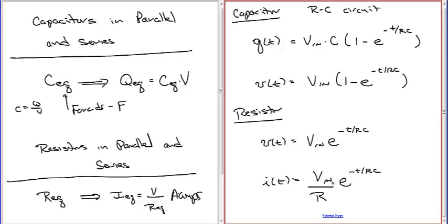So just be able to, if I give you voltage, capacitance, resistance, and I say at time t equals some seconds, to be able to calculate all these quantities. And you have to remember at any time that this plus that has to equal the input voltage.